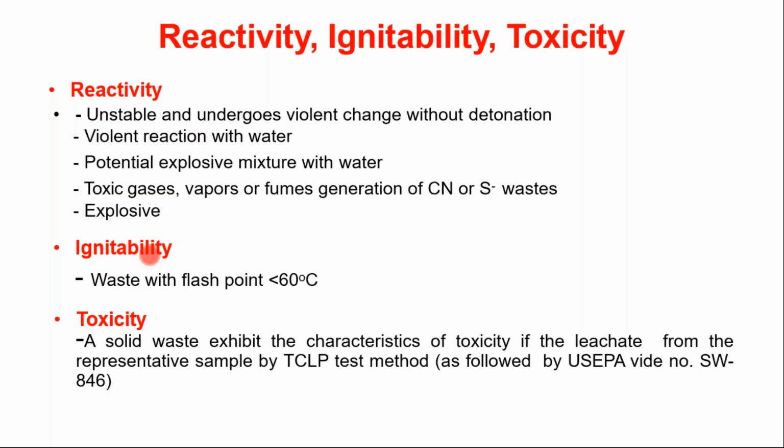Then ignitability. Ignitability is the property that comes from ignition. Ignition means something which can cause fire or a spark. So a waste with a flash point less than 60 degrees Celsius possesses this property, which is called ignitability. If the temperature is less than 60 degrees Celsius and the waste can catch flash or fire, then that substance is called an ignitable substance, and that property is called ignitability.